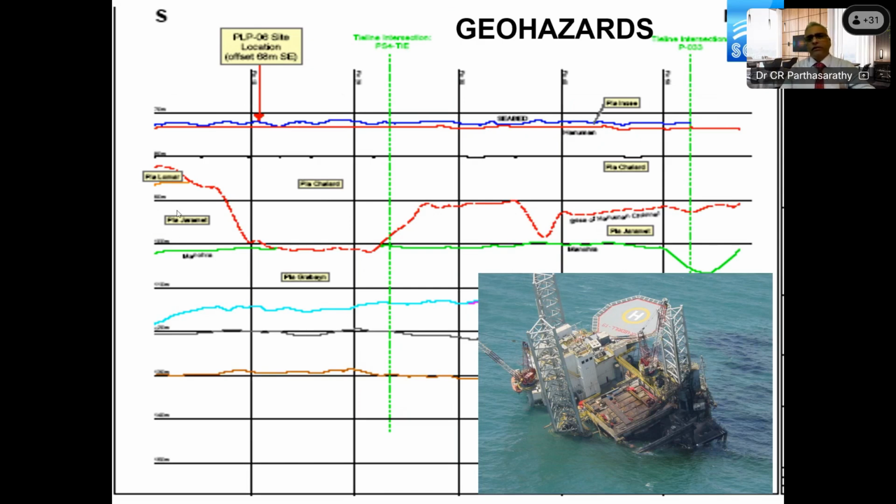So invariably in the offshore environment, particularly whenever the rig is moved to a location, you perform a geophysical survey ahead of the geotechnical survey. And that's the normal procedure. But we have seen at times the planning is not so advanced, and you will have the surveys being done in parallel, the geophysical and geotechnical. So before you get the geophysical results, the geotechnical borehole is already performed.